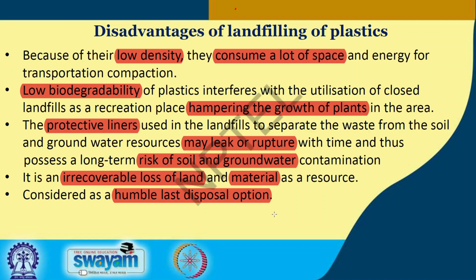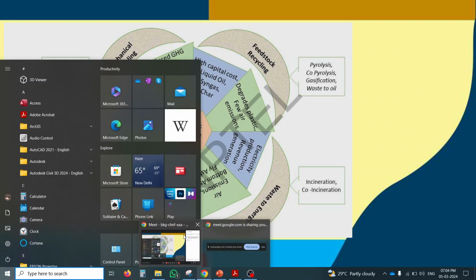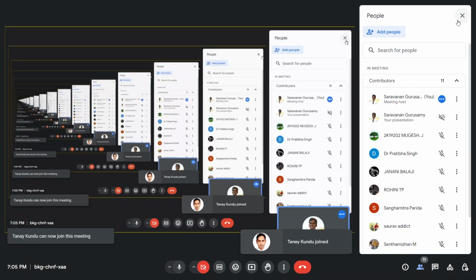That's what we can say. If nothing is available, we can't reuse, we can't recycle, if we can't recover any energy, then as the final option, for inerts we can think about landfill. For plastic, we should not even think about landfill as an option for management.